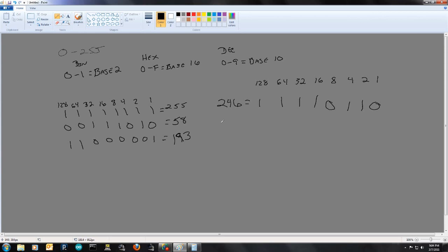Okay, let's take another number in binary. Now, if we were just doing 4 bits, we're actually going to be using shift registers eventually. Like I said on the Arduino, we have some digital pins, and you can get an Arduino Mega and control 54 digital pins, so you can control 54 individual LED lights. We're going to have a lot of projects using LEDs, but we don't want to use all our digital pins to control them. So we're going to use something called shift registers. And these usually work on binary, so we'll actually get into that. And they usually work on 4 bits.